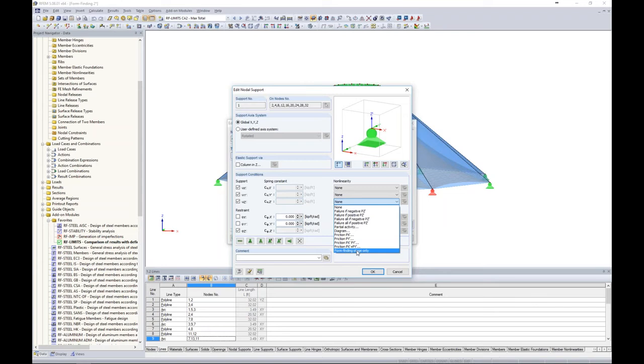Then when we move on to, let's say, our ASCE 7 load combinations, those constraints are no longer taken into account. They don't exist at all. So this is almost like a construction type phase that we can automatically account for within the program. So just a nice powerful feature rather than manually having to do this.